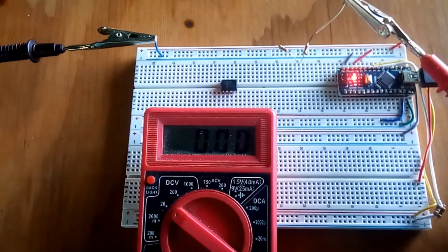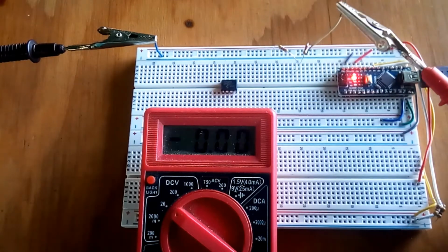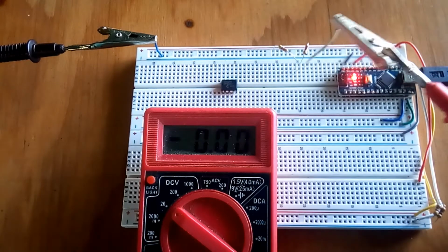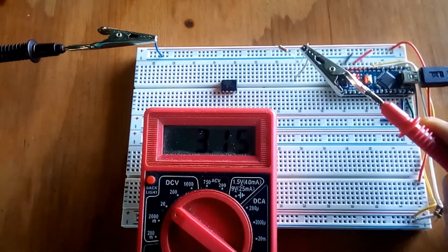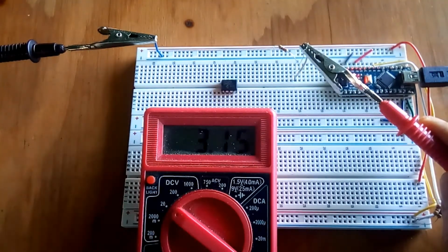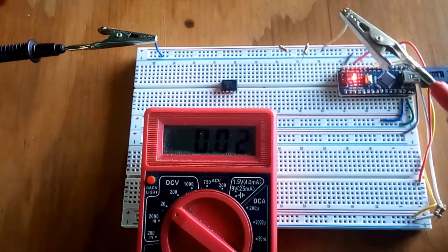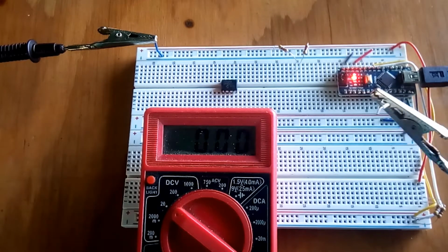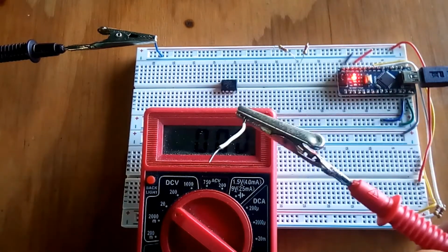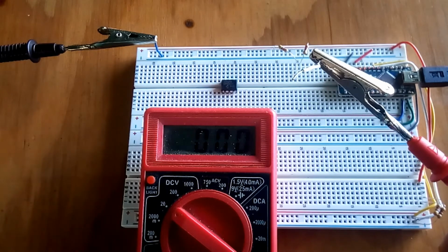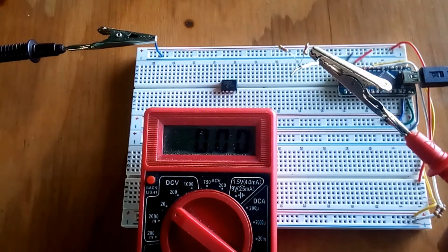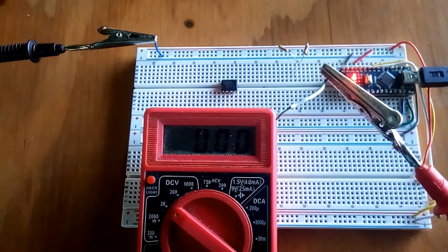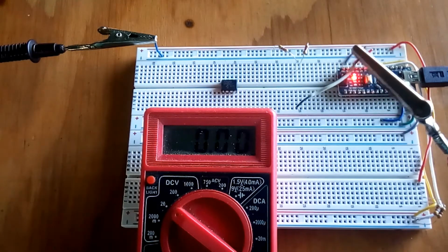So here I have a 2200 ohm resistor burning up some of that voltage. Then it goes through a 4700 ohm resistor to burn up the rest of the voltage. And right in between them is the range I'm looking for. So 3.15 volts. That'll work perfect for the chip. So just a voltage divider. It often happens with microcontrollers, we need to turn the 5 volt range into the 3.3 volt range. And a quick voltage divider to get that is going to be a 2.2 kilo ohm resistor followed by a 4.7 kilo ohm resistor. And that just adjusts the voltage to the level we need.